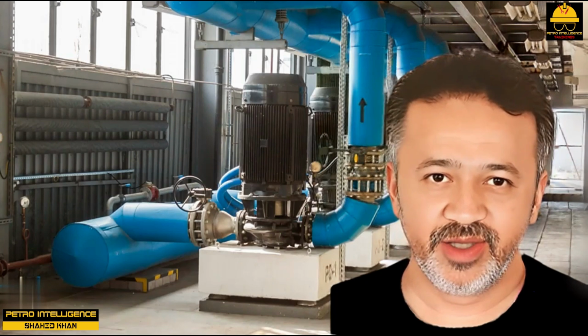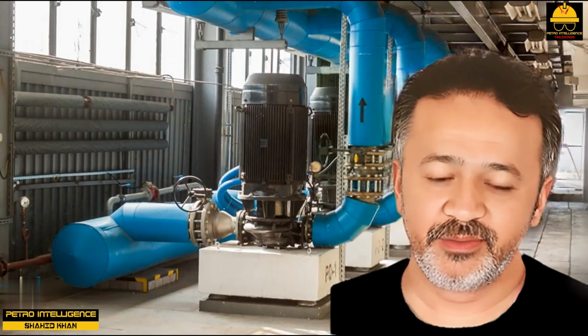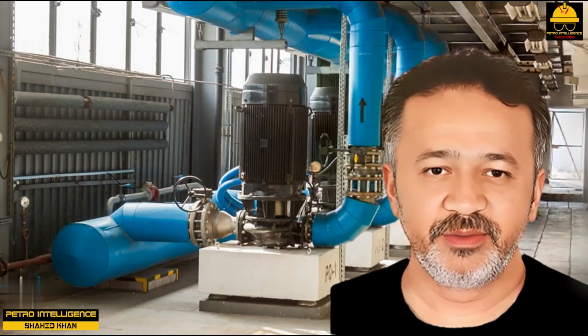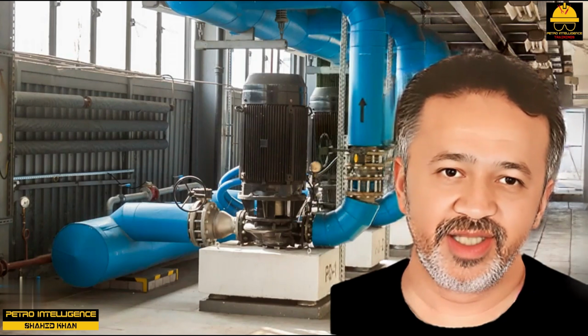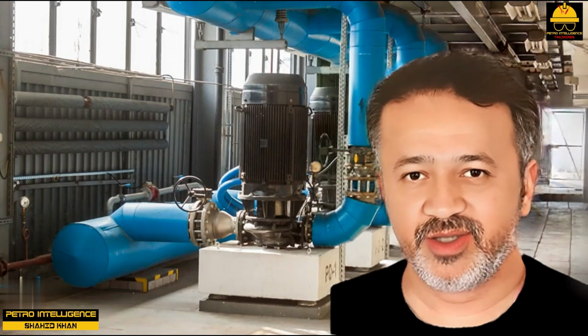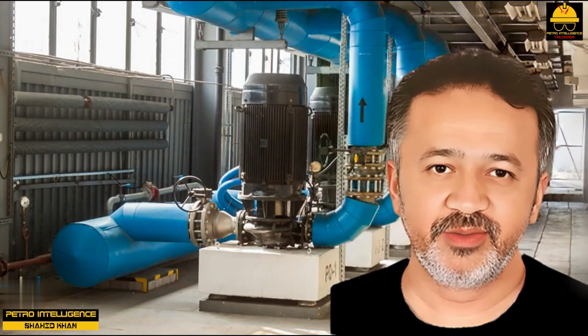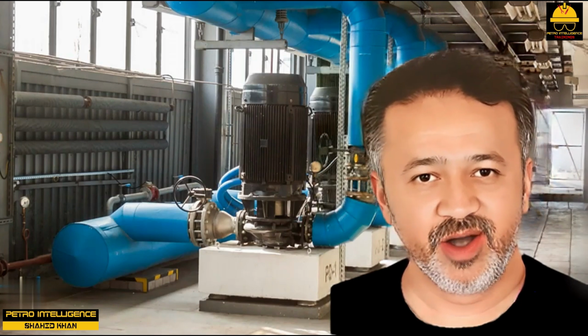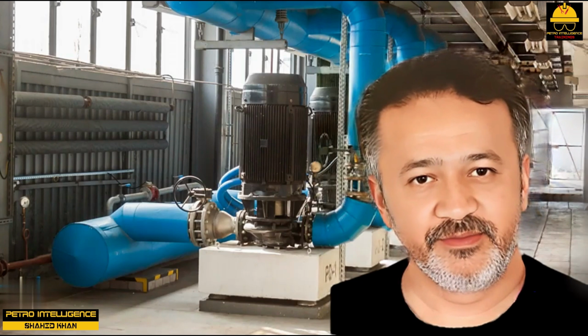Increasing the size of an impeller always increases its maximum discharge pressure. Hence, increasing the impeller diameter may be unlawful, depending on the maximum allowable working pressure, MAWP, of downstream heat exchangers. The MAWP is shown on the exchanger nameplate.